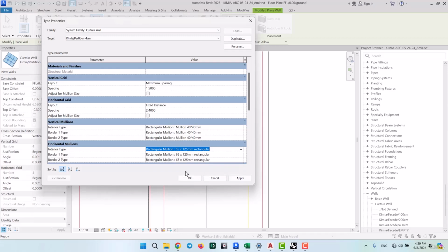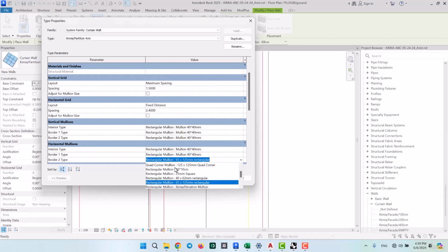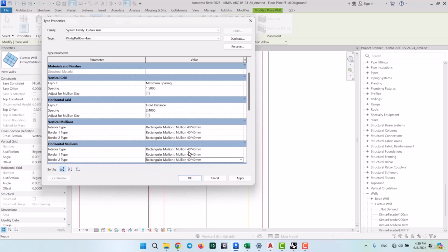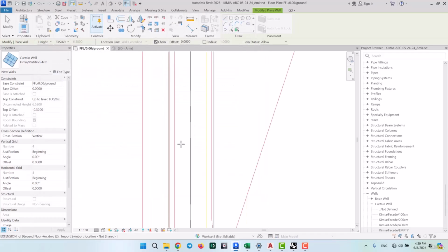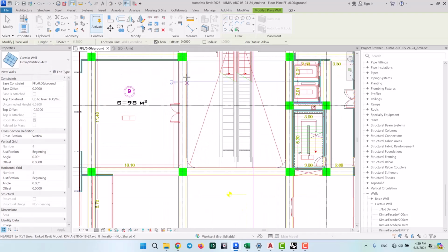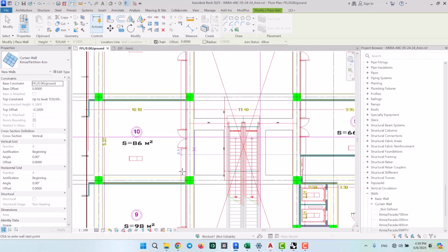because basically for these curtain walls or the partitions that we're going to be drawing here, we don't have a fixed amount of distance between them. Each of these partitions have different dimensions, and so for parts like the beginning and the end, and the part in between, which goes for the door, we will need to place some vertical mullions, and because of that, we can't just get an objective pattern for how everything else should be. We can also see that the dimensions differ here. Therefore, you'll have to put the time and place your mullions manually.